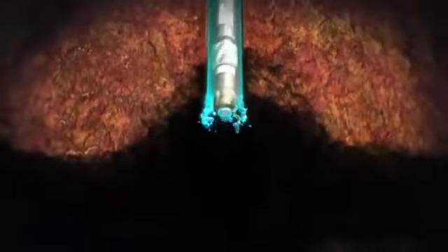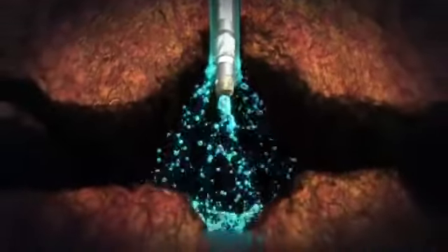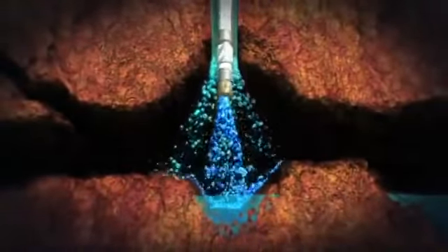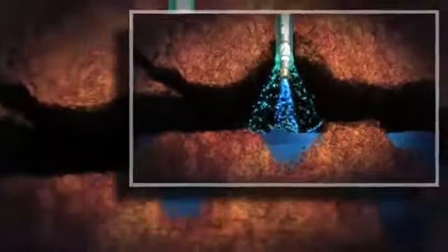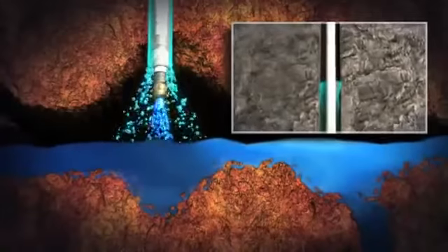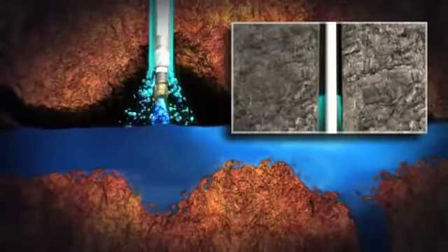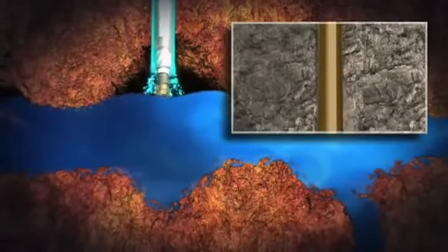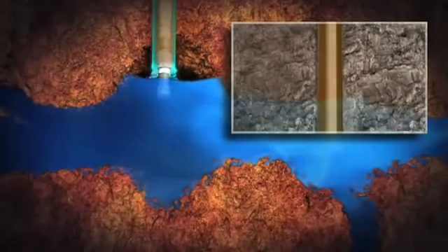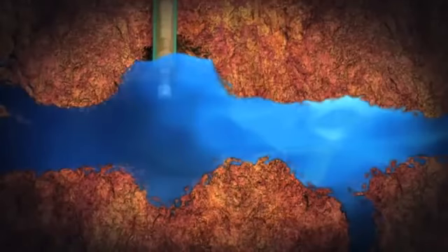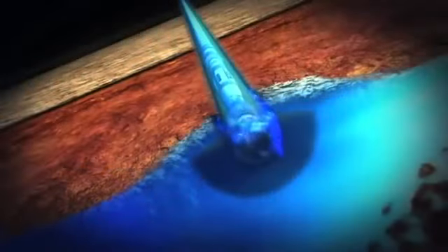As illustrated in this scenario, as soon as the fractures are encountered and drilling fluid is lost, the well annulus is closed with the RCD. Sacrificial fluid is pumped down the drill pipe, and a fluid cap, often just plain seawater, is injected into the annulus or circulated into place via the casing. With the casing shut in, the weight of the fluid cap is balanced with the formation pressure by managing the surface pressure. Casing pressure and gas migration is quickly and accurately managed through application of surface pressure and by adding or removing fluid from the top of the fluid cap.